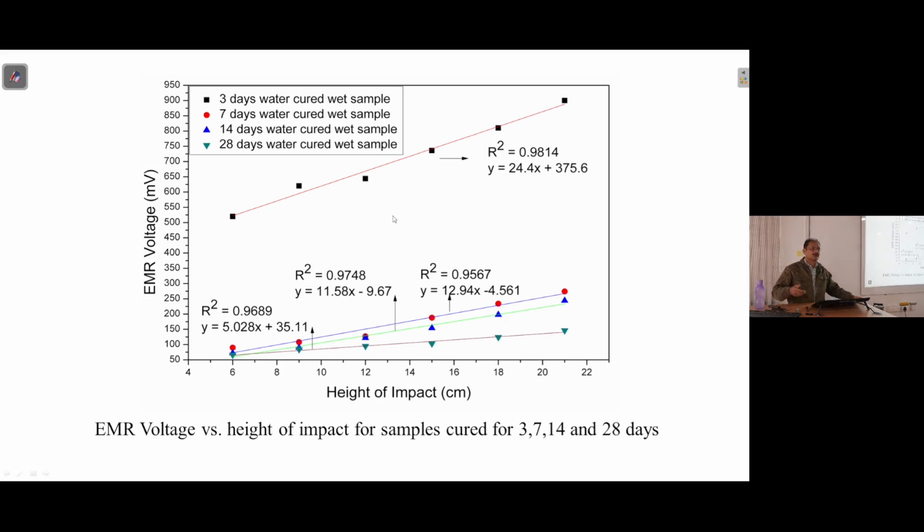At least for 14 days they are kept as such, and thereafter you proceed further, because it takes time to attain the strength, any cement based structure. That is because this reaction actually takes a longer time. So effectively, as that continues to occur, it gains strength.